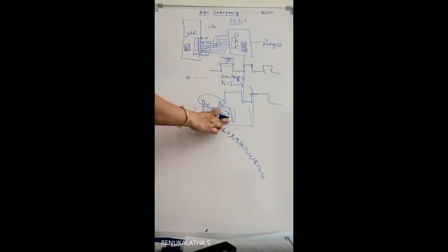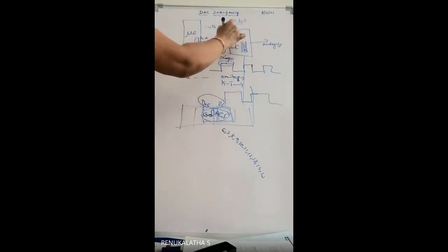It is a 32-bit register which receives the data sent by the port from the microcontroller. Among the 32 bits present in this DAC register, only the bits D6 to D15 have the valid meaning, totally 10 bits. Then this will be converted into analog output. The digital data that arrives, by using a suitable circuit within this, will be converted into analog output.